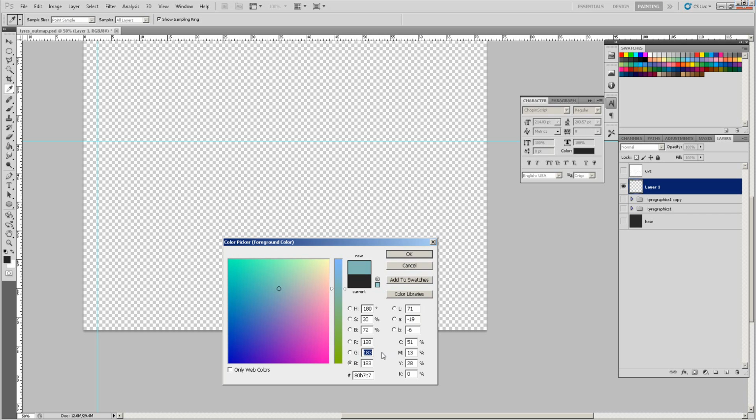Now the range is 256 between white and black within the grey range, and bitmaps are based on grey range colours. So midpoint 128 would be no distortion at all. And then going back to push into the model, you would use black or degrees of black from 128 back to 0. Obviously white would push out, so from 128 to 256 would be degrees of push out.